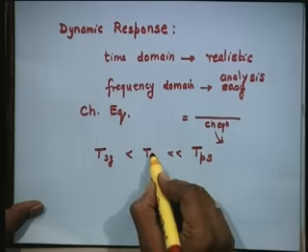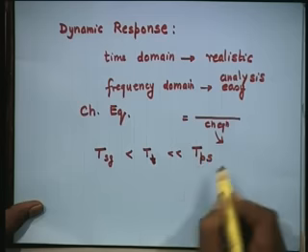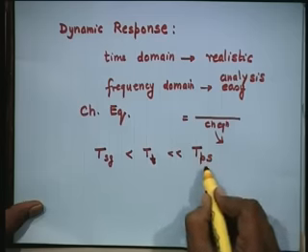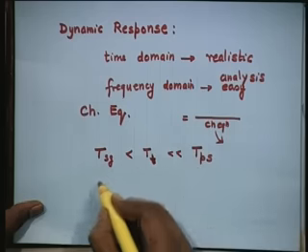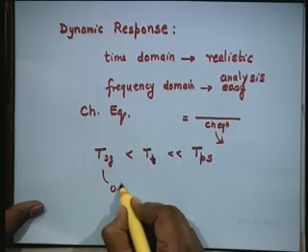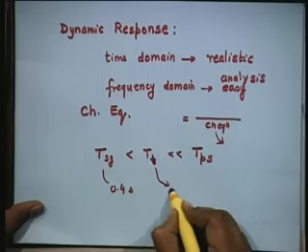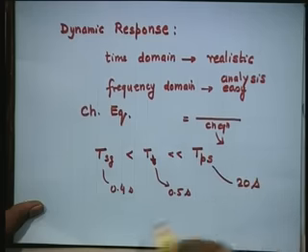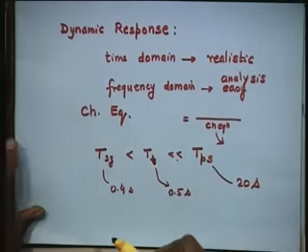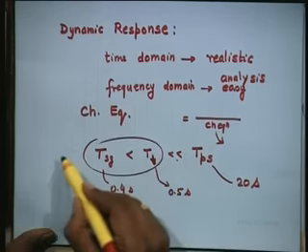What is t? Turbine. What is T ps? The time constant for the power system. Now, typical values, if you want: T sg is 0.4 seconds, T t is 0.5 second, and this is 20 seconds. That is why much less than. So, we can put these to 0.